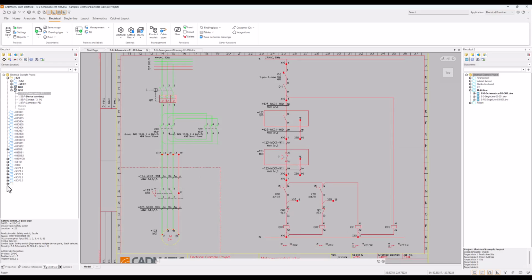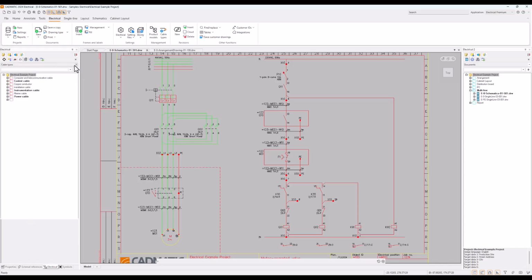Now you may wonder how can you find things in the project database. There are quite a few blue directories and some other icons. In this training, as mentioned, we use these devices and location, and you can change those from the drop-down menu. You can create this in a way that you want. Maybe you don't want cable types, maybe you want the IOs and circuits.